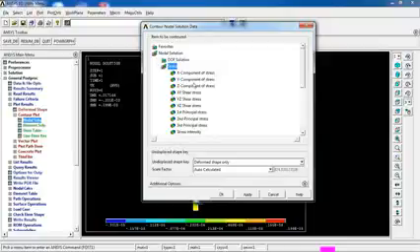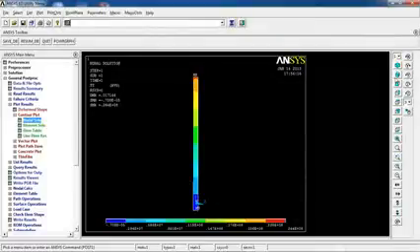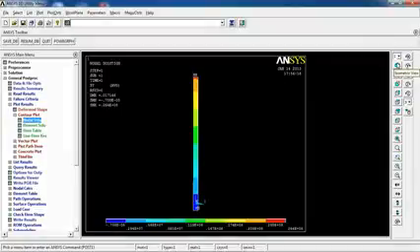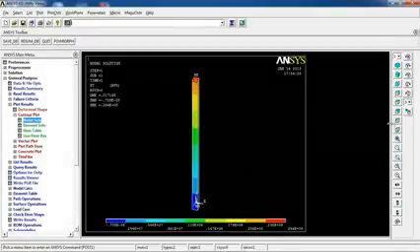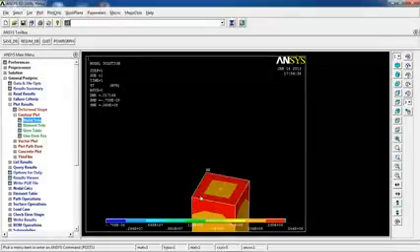And then let's see stresses in Y direction. Again, it's somehow similar to what we saw yesterday, except for today, because of my meshing, it's not as precise as the model in lesson 7. But something you want to pay attention to is the fixed end. It's not a constant stress in here. As you see in the middle, there is a little bit difference compared to the edges of the sample.